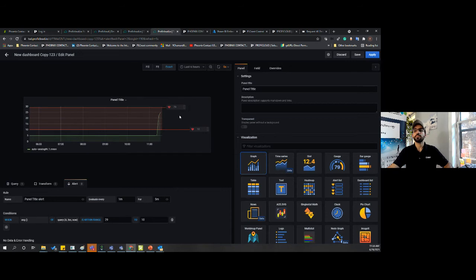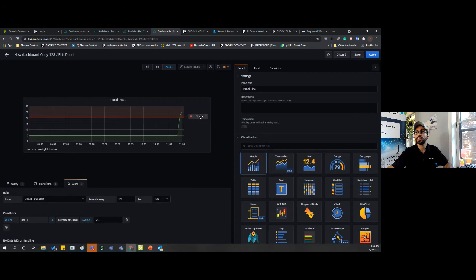It's pretty cool the way we set up alerts. It's easy. It doesn't get any easier than that, if you will. Okay, so I'm just gonna go with the classic above, and I'm gonna say that if this thing is above 27 for 1 minute, we get an alarm.